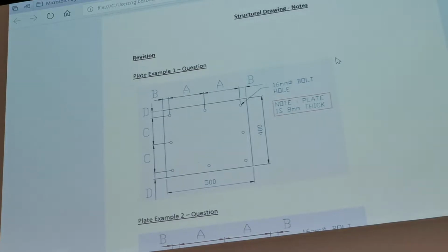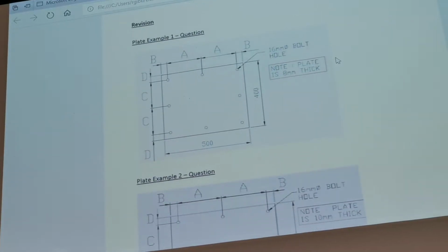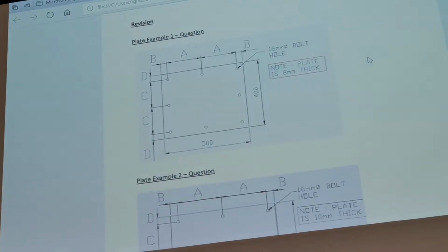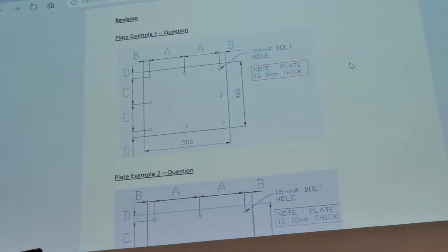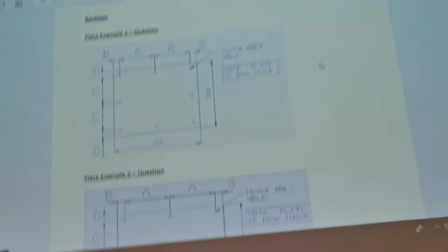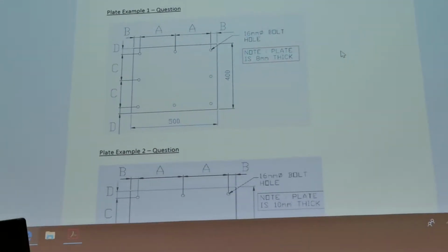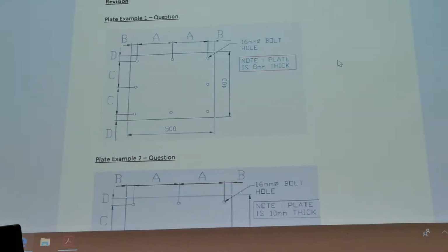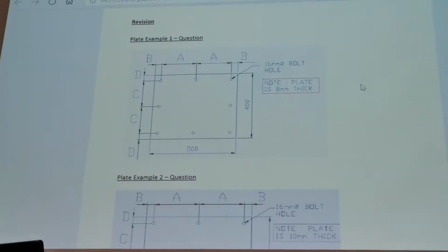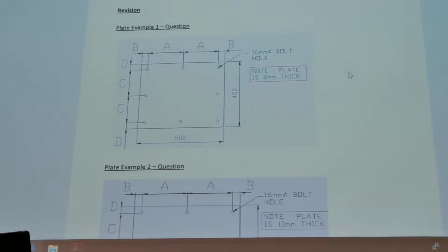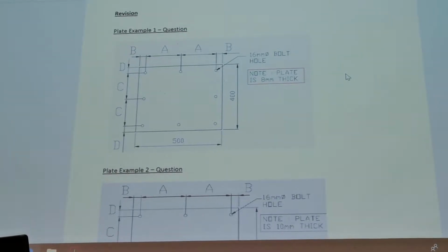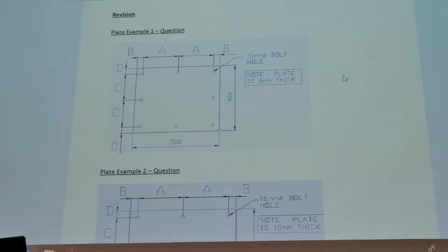All right. Okay. So with the plate design, you need to remember me talking about Grandma's quilt and Grandma sewing around the outside edge, and I said that with reinforcing. Unfortunately, a lot of you didn't take that into account when you were doing the reinforcing. You always put the bars as hard as you can against the edge.